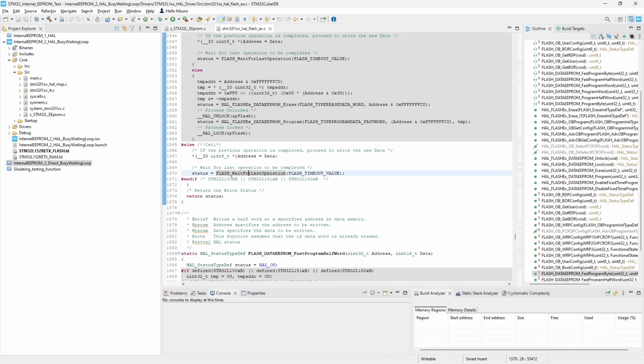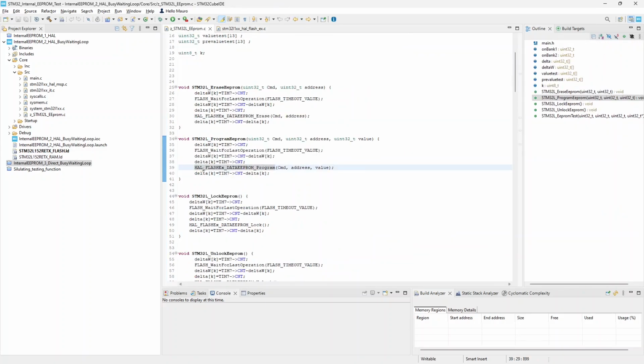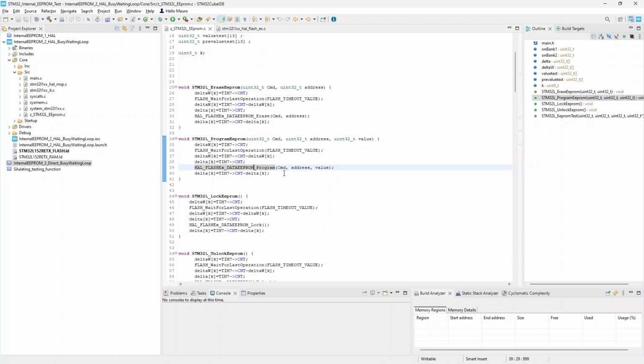Even if we could proceed, the HAL function loops, waiting for the confirmation of the writing complete. Regardless of whether the writing bank is the same as the running program bank or not, the HAL function loops until the writing is complete. There is no parallelism between the two banks involved. So I set up a third test.